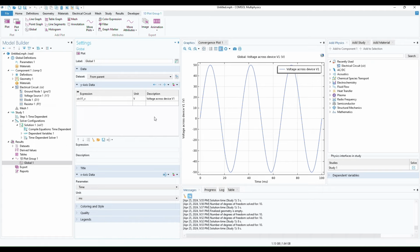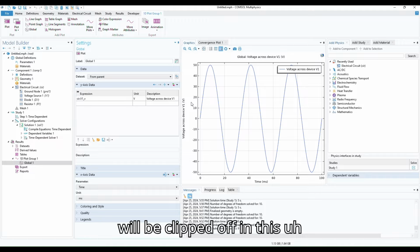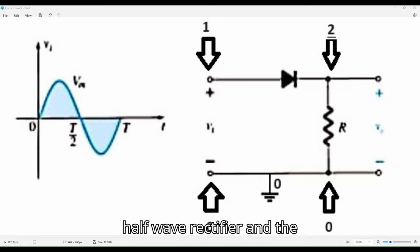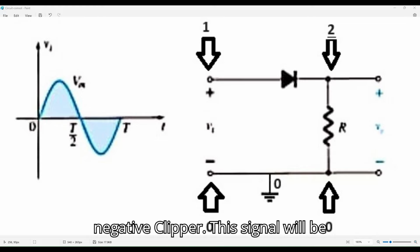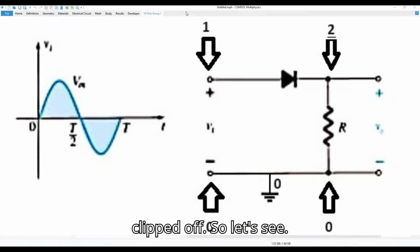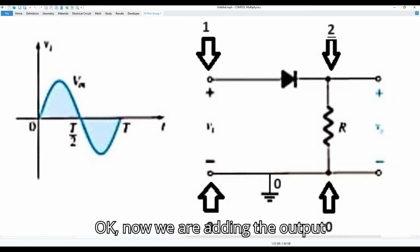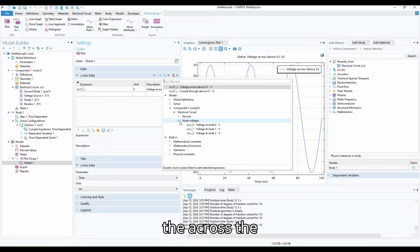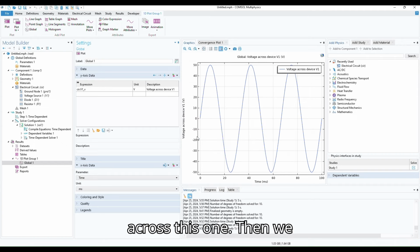Now the output wave will be clipped off. Part of the input signal will be clipped off in this circuit. You can see over here, this is the half wave rectifier and the negative clipper. This signal will be clipped off. So let's see. Okay, now we are adding the output signal. The output will appear across the resistor R. So we are considering the output signal across this one.